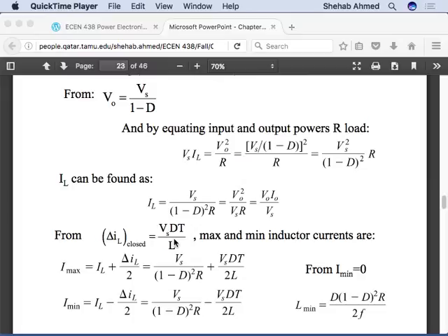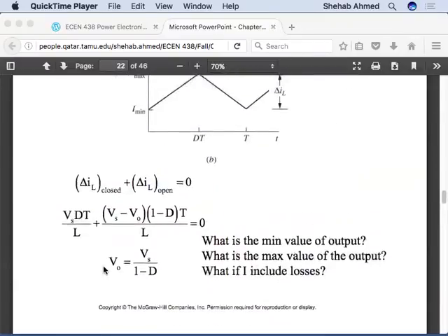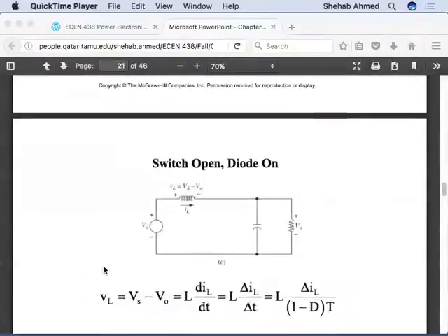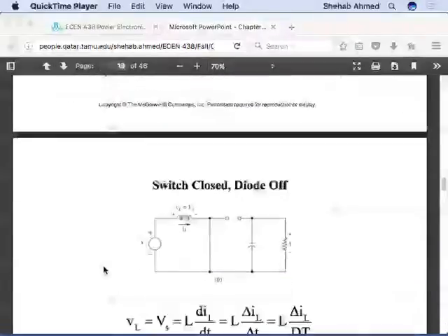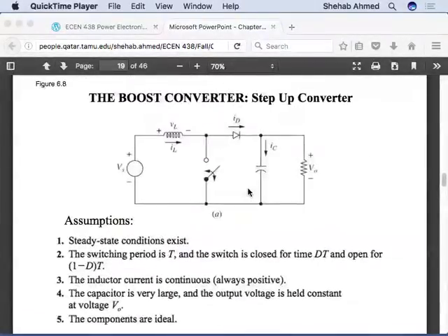Exactly, it's the area under the current curve, which is charge, divided by a specific voltage ripple spec. So inductance and capacitance are very easy to calculate here. Okay, so how do we come up with the minimum value of current? Let's first go back to the circuit. This is my circuit here.